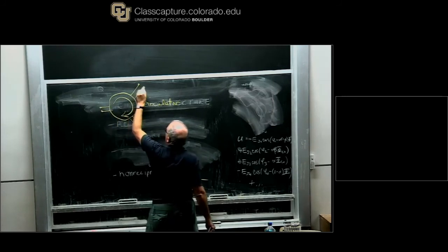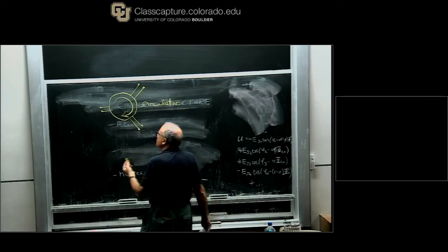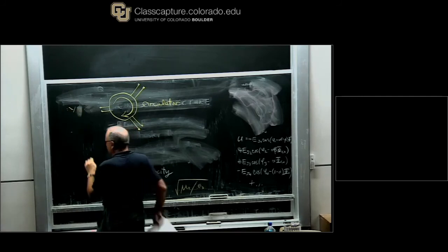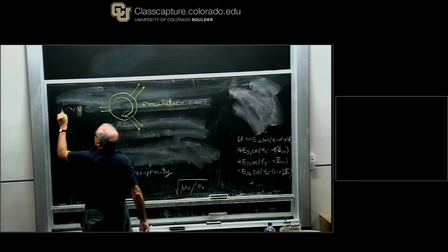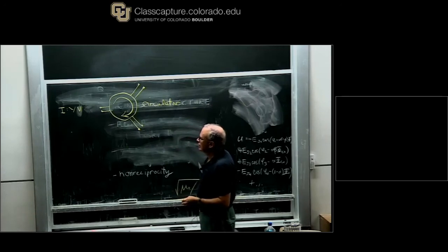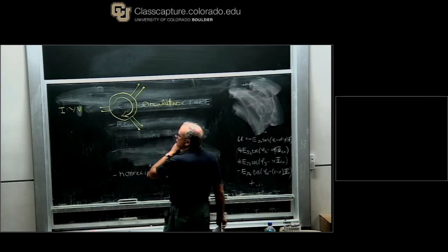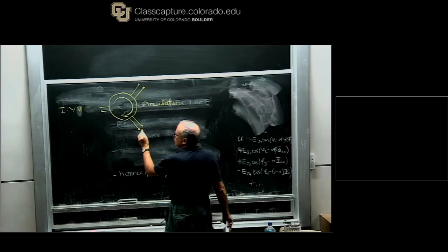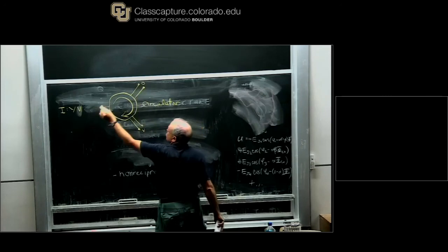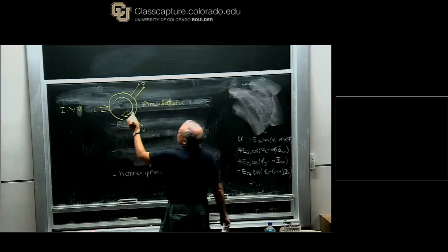One way that it's stated is to ask what's the admittance matrix of this. So what that means is that I apply, remember admittance, I always have to think for a moment, YV, right. Admittance means I have voltages applied, and I have current outputs. And the strange behavior of the circulator is the following, that if you apply a voltage here, so a voltage difference between these two terminals, but apply no voltage differences here, you nevertheless get current flows, which are of this character.